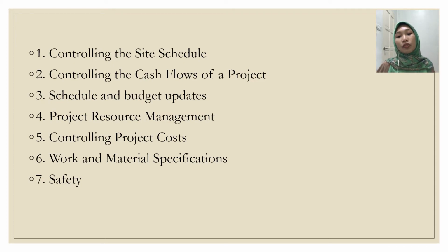Safety. Various measures are available to increase building site safety. Several of the most important occur prior to the start of construction. Design and technology selection and education are among them. Specific structures can be made safer or more hazardous to build by changing facility design. For example, SOPs that need to be followed on site include wearing hard hats and eye protection on site, requiring hearing protection near loud equipment, ensuring safety shoes for workers, and last but not least, providing first aid supplies and trained personnel on site.